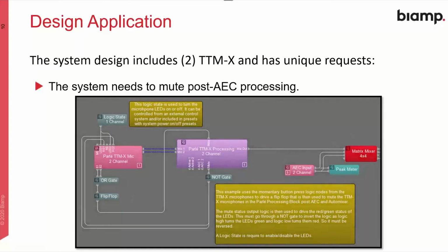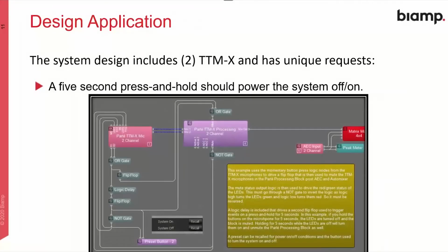So moving on, the 5-second press and hold for system power on and power off. You'll notice a lot of the logic is the same here, but we're actually taking that output of the OR and driving into a logic delay. That logic delay has been configured for a 5-second on. So after it senses a press and hold high signal for 5 seconds, it'll actually pass through a logic high